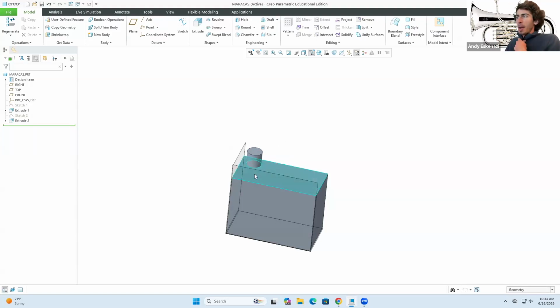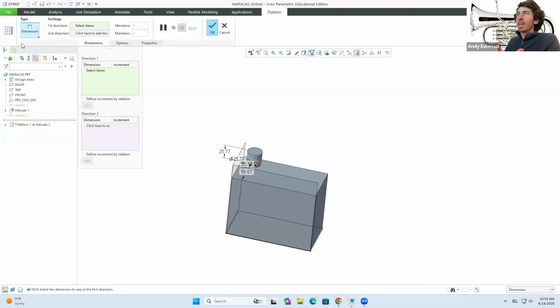Well, you have something that looks like a brick, but you may have seen Lego bricks in the past, and the one that I'm trying to make here is a 2x4, as an example. So how do you make that? Well, you have this little peg here. What you can do is click on extrude number 2, and you see how the minute I click here, this command unlocks itself. This is called pattern. You click on it, and there is a multitude of different options that you can choose from.